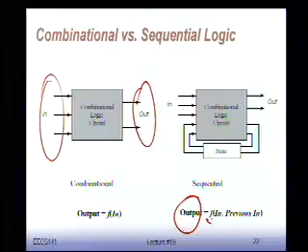It has memory. For instance, if you look at your FIR filter, it's a 5-step FIR filter. We know it's going to remember at most 5 time slots. You put something in your delay chain, it goes through, and after 5 clock cycles, it disappears. That's why it's called a finite impulse response filter. It has a memory 5 levels deep, because there's no real feedback in that thing. It's only feed forward.